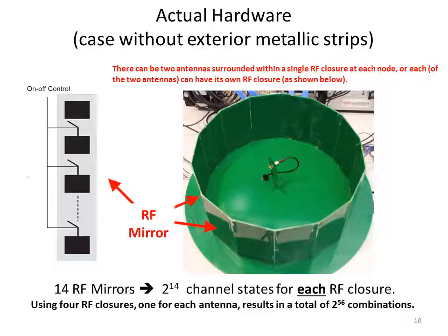And again, this is a new design. It has not been reported something like this, that we have a reflector that can be controlled to either reflect or become transparent. Now we have this antenna in the center of this closure. This is a monopole, will have a donut shaped transmission pattern, antenna pattern.